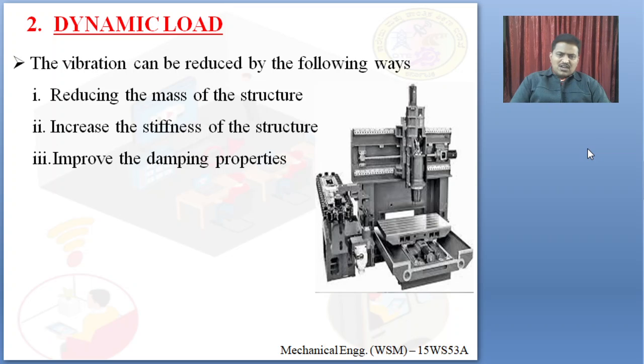So these are some of the remedies that can reduce the vibrations. First one, reduce the mass of the structure. What is that going to do? Reduce the unwanted mass, not the entire mass. It is the unwanted metal, where the metal is not required and has no function. Reduce it, so reduce the stress concentration factors in that area. Remove unwanted and non-functional parts. So reducing the mass of the structure is one area.